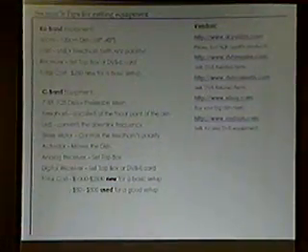Now, tips for getting equipment. KU band equipment, which we just talked about, the free-to-air stuff. 60 centimeters, 120 centimeter dish, 18 inch to 45. That's basically the size you'll need. The LNBF and feed horn with the horizontal and vertical polarity, which they use, will cost you maybe 30 or 40 bucks. Receiver, set-top box, or DVB-S card can cost you about 100 bucks, maybe 200. Total cost about 250 new for a basic setup.